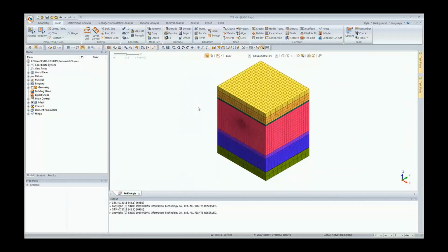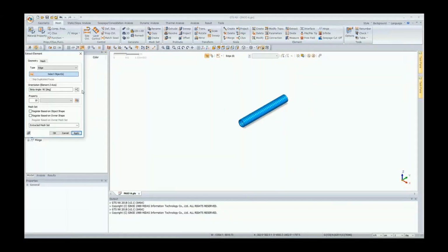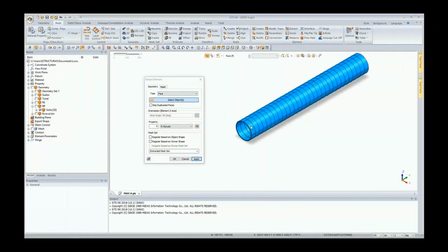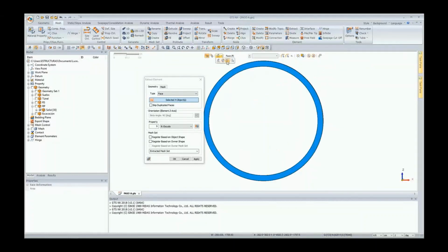To do that, we are actually just going to do it by selecting the faces of the geometry. It's a lot faster than selecting the meshes. So I activate the outermost tunnel rings, which is the primary support, and then I use the command extract. And I select the faces that correspond to the outermost face. So we see here these are, clicking on them is one way to manually select them. An alternative way is I can select this other filter that we have, which is like a polyline selection.